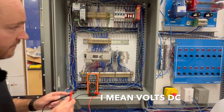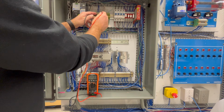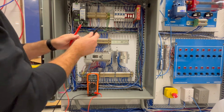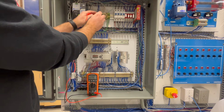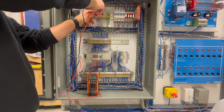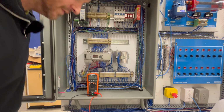Once I'm on 24 volts DC, the first thing that I want to do is come here and check to make sure that I'm actually getting 24 volts and my meter is reading. So I'm going to come over to here, and you can see that I'm getting 24 volts. So I know that I have 24 volts here.